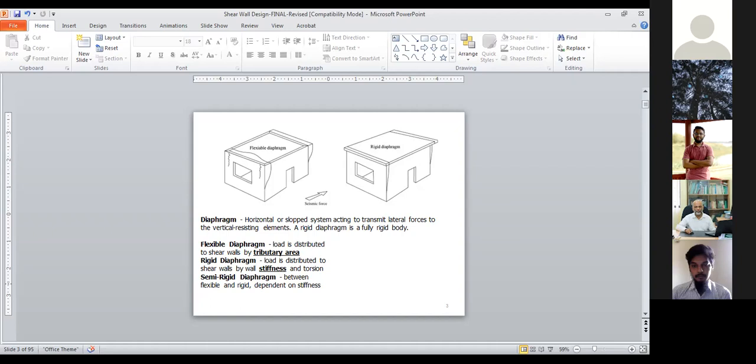Anyway, if you have that system, I think your software can take care of that transferring of the shear forces in the shear wall system. But once again, most of the time your slab is very highly resistant in plane, very stiff in plane.